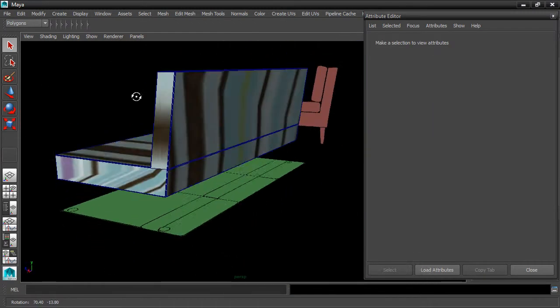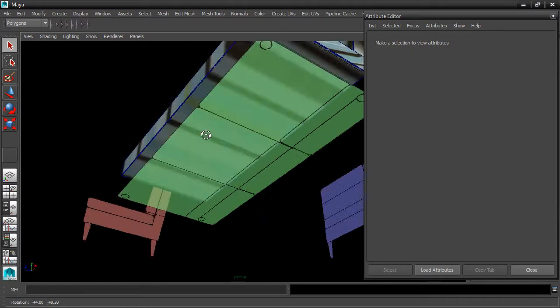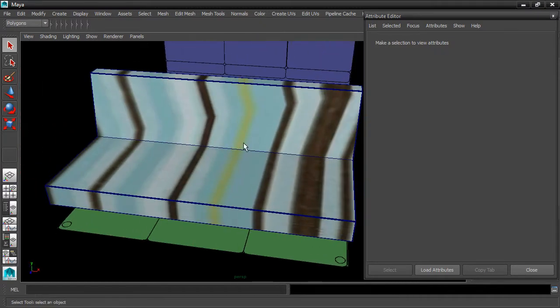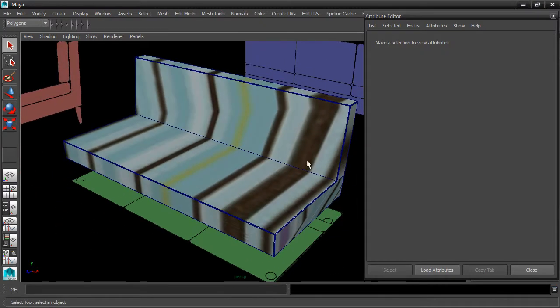And you can see it looks pretty terrible. We have all kinds of stretching and all sorts of issues. The size is all wrong as well. We want it to be consistent and properly scaled. To do this, we go into the UV texture editor. But first we have to have some base texture coordinates on here to work with. Right now it'll look dreadful if we go into the texture editor.